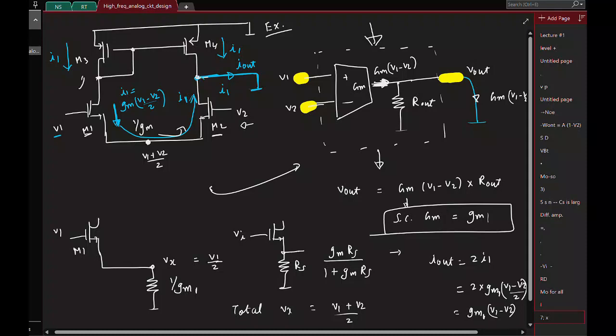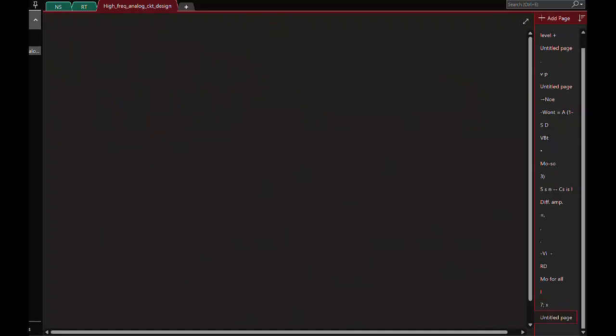Here also, if you think about it, what is the impedance looking up? It has rds, but also has a contribution due to the gm block, right? So I'll show it here. You have a configuration like this, so let's say you apply a test voltage here to find the impedance. Between drain and source you obviously have gm VGS, also the r0 of the transistor.